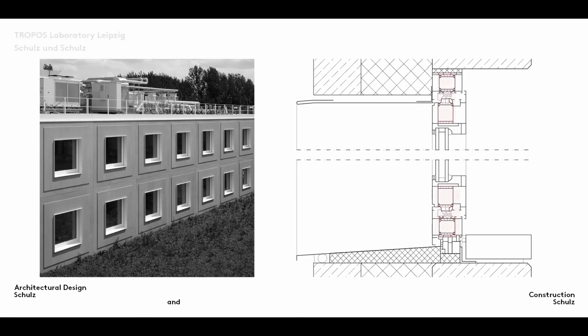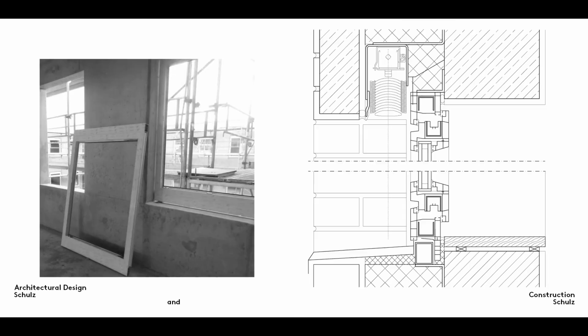Aluminium window frames have a thermal break that reduces the level of heat transfer. Inner and outer frames are connected by means of a plastic strip with a much lower heat conductivity than the aluminium. Aluminium windows also weigh less than steel windows, are less costly to produce, and are resistant to aging without maintenance.